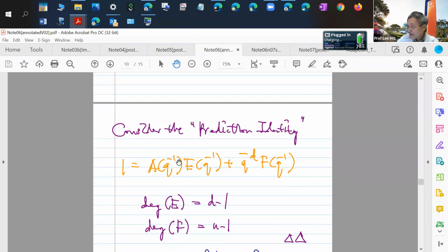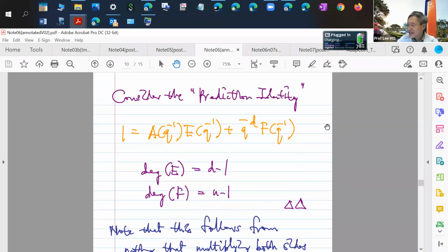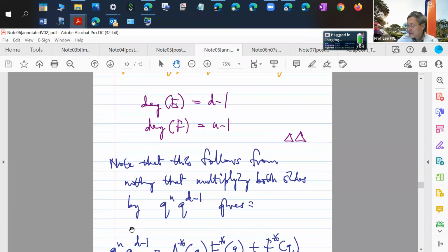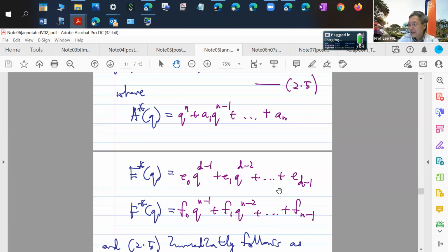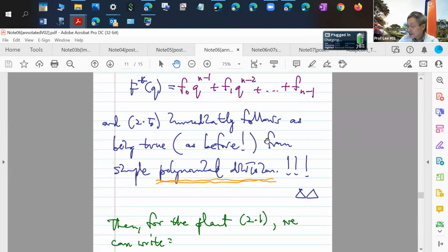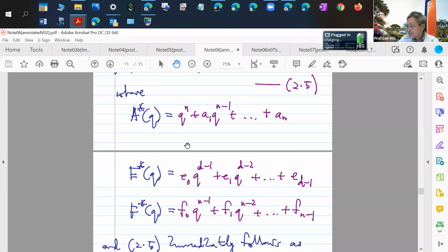In fact, there's an equivalent so-called identity, except that you don't see that it is the same as what we had before because you're working with a backward shift operator. All right, until you say, look, just go ahead and convert everything properly, so that it looks the same as what we have. And to convert it properly, you basically take the whole thing and multiply through. And when you multiply through, you will see that you are left with equations in the forward shift operator. All right, and the moment you have equations in the forward shift operator, you take them and rearrange them.